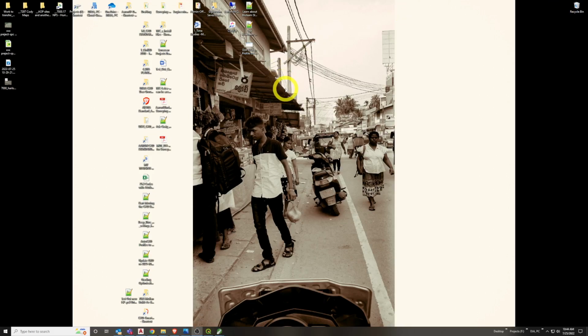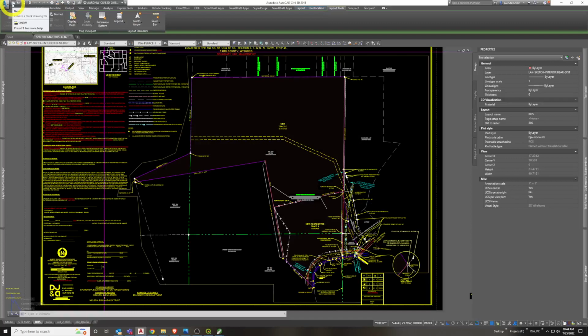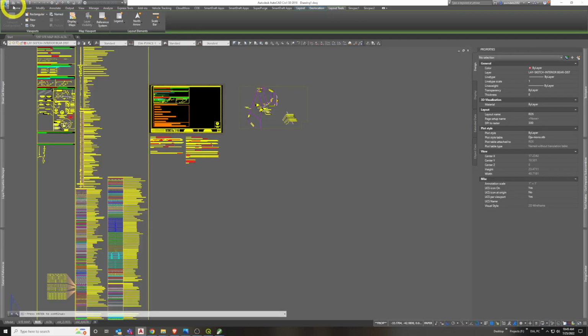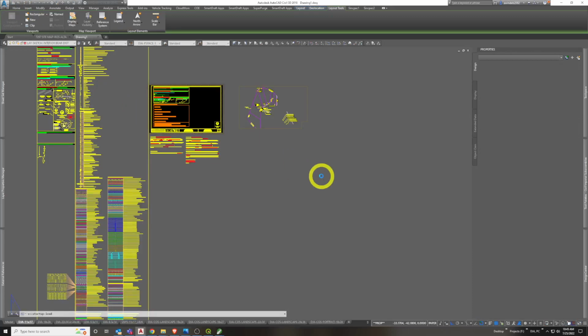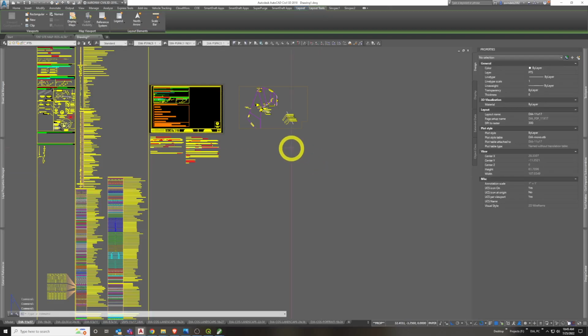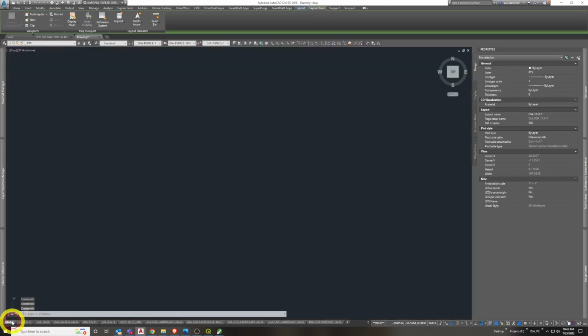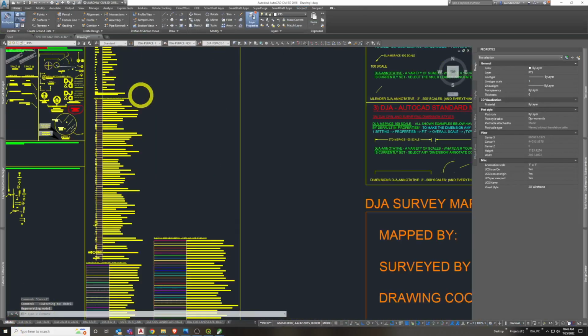So let's take this image and put it into CAD quick now. In this case, I'm just going to be in 2018 Civil 3D or AutoCAD. I'm going to hit QNEW or new. It should go to your survey template or whatever template you're linked to that is live and active. This is a good way to start. We'll go to model space to get ready.